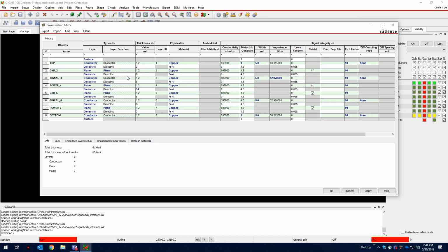Are there multiple ground planes? Here there are two ground planes, so that's satisfied. This will help to lower the reference plane impedance of the board and reduce radiation. And then lastly, are the ground and power planes closely coupled to increase the interplane capacitance? The plane pair in the middle of the board is not really tightly coupled, so it could be an issue here with your power delivery.